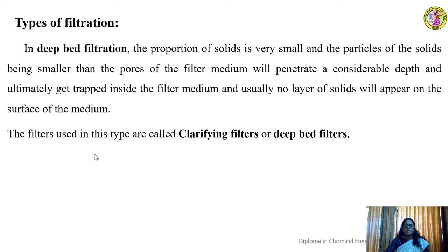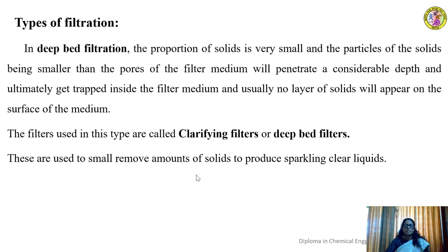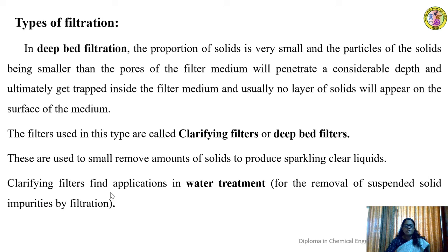Whichever filters employ this kind of filtration operation are called deep bed filters or clarifying filters. These are used to remove small amounts of solids to produce sparkling clear liquids. Clarifying filters find limited use in the industries.